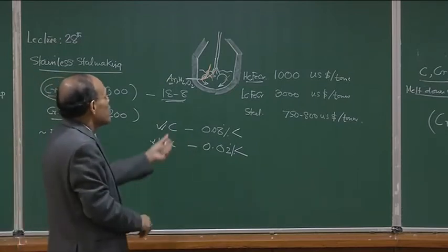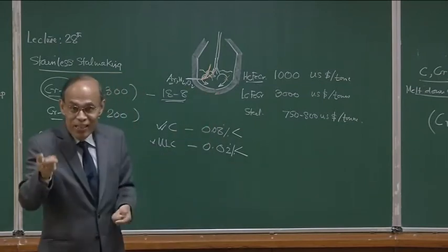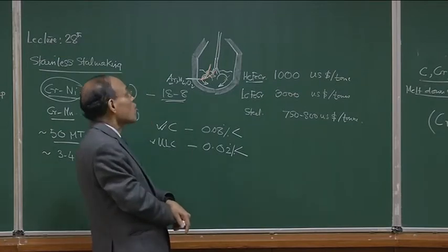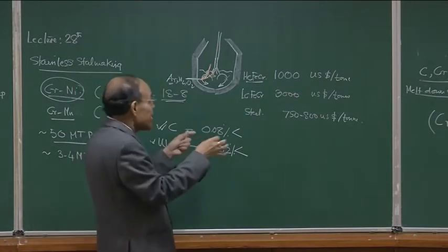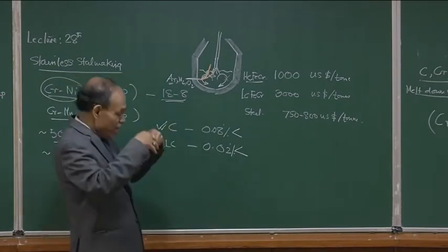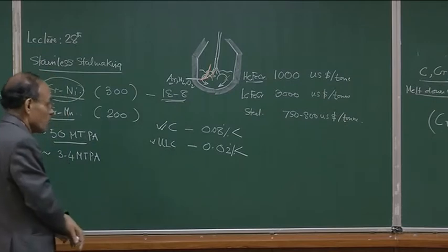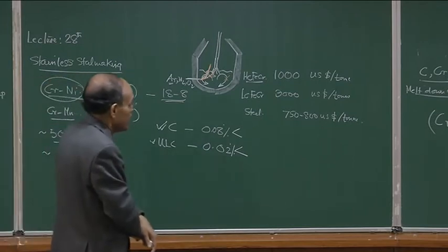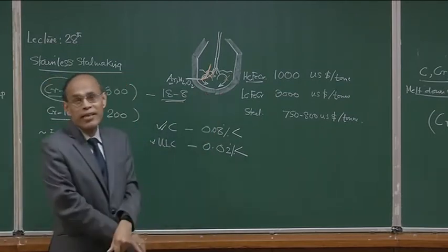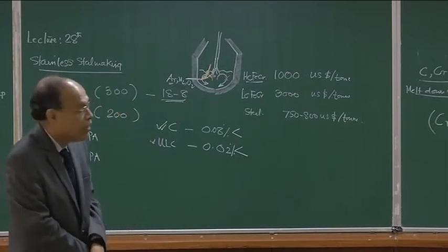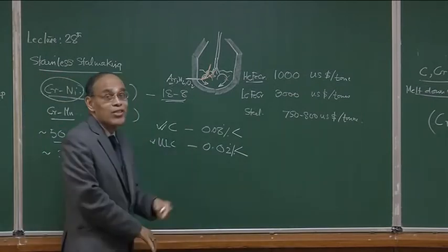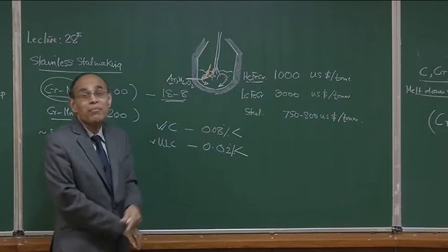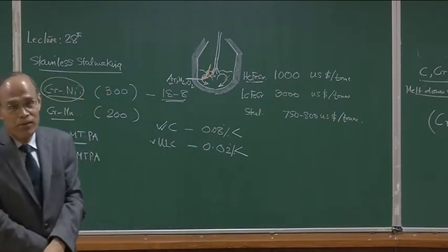That is one limitation, and that is why, even though you have carried out melting elsewhere, the rate of carbon oxygen reaction is not appreciable, decarbonization rates are not quite appreciable, because you do not create a very large interfacial area, you do not create a very large velocity in the system, which are essential conditions for achieving higher decarbonization rate. As a result, the tap to tap time here could be quite long in comparison to, for example, the basic oxygen steel making converters. Even making 30 to 50 tons of steel may take 70, 80, 90 minutes of processing in the converter.